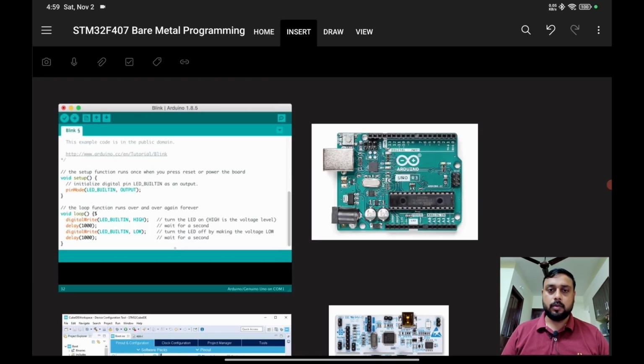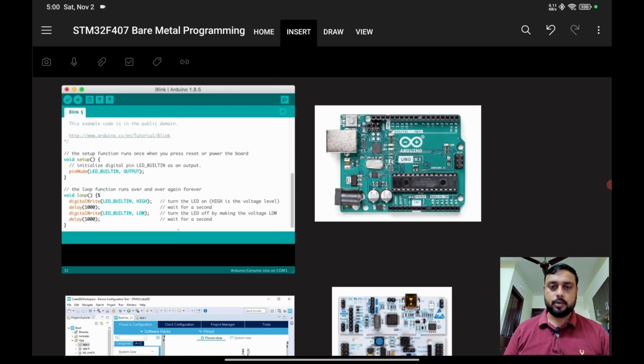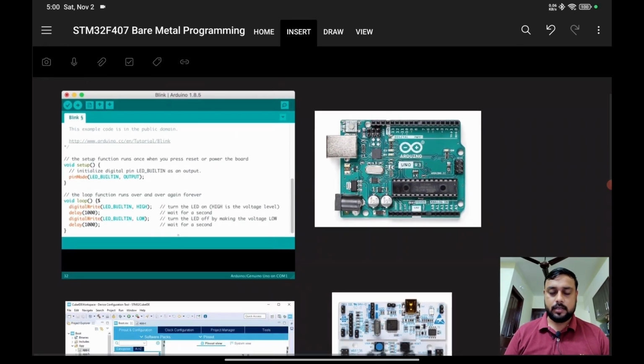and then you need to know a little bit about the different software, basically the compiler, assembler, linker, what the debugger is, how we do the debugging. A little bit you need to know about the controller architecture. At the very core we have two kinds of architecture. One is the Von Neumann architecture, one is the Harvard architecture. Then every controller is different from each other, although the basic principle they follow is these two architectures only. But a little bit of these ideas you should have before starting this session.